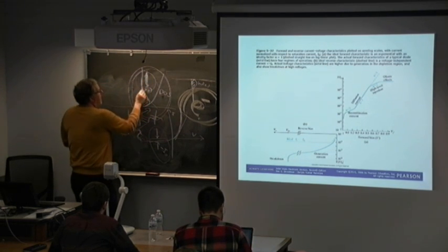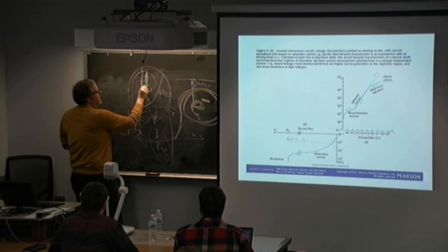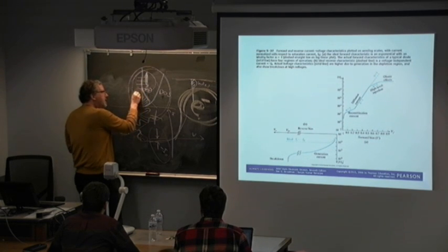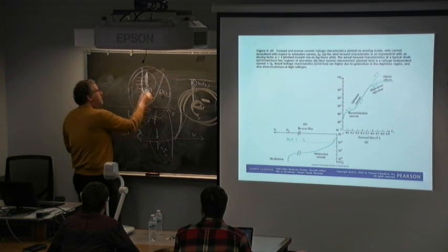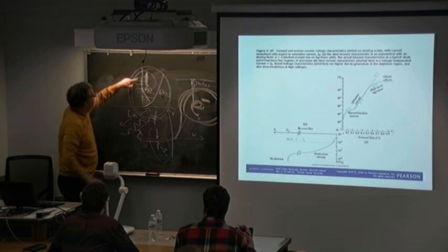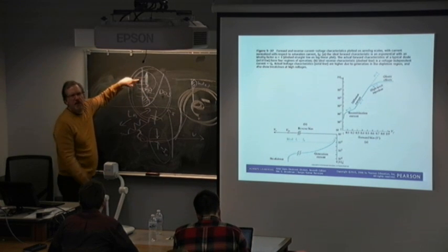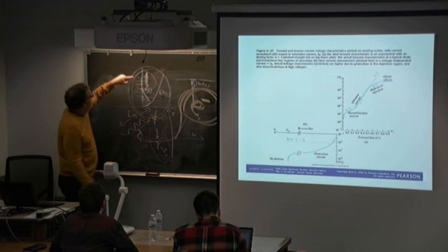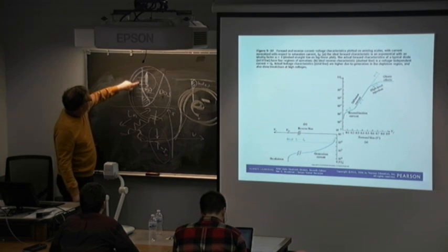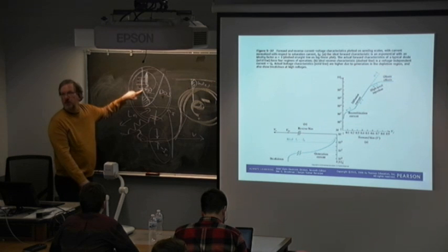At first there's nothing, then still nothing, and then it starts to see something. So think of this as increments of half volts, or 0.2 volts. 0.2, 0.4, 0.6, and around 0.7, boom, something starts to happen.